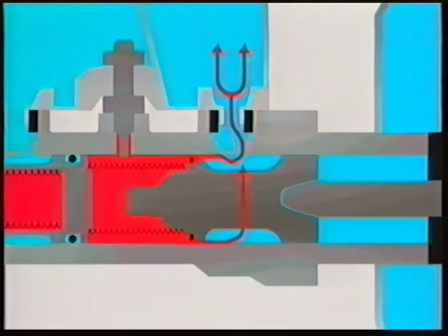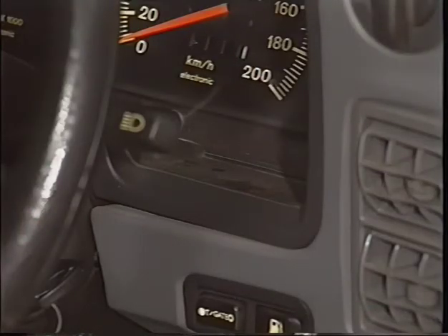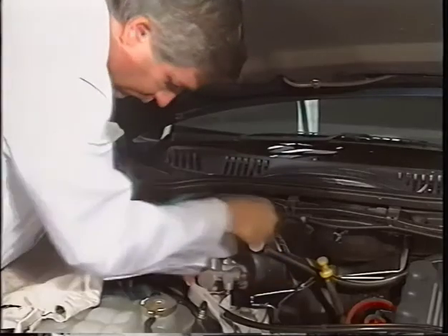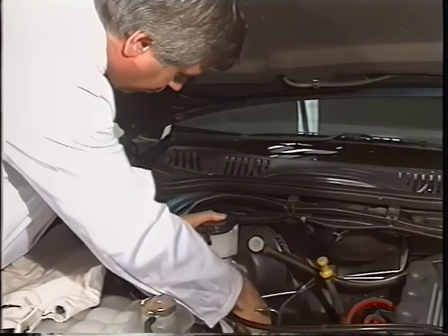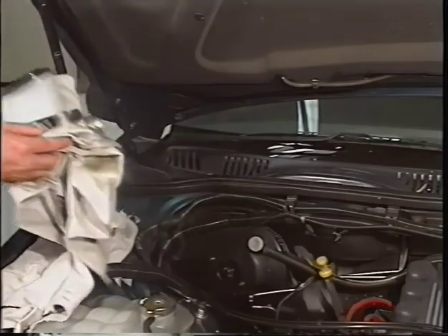Also, on conventional as well as fast-fill master cylinders, internal leakage between circuits or over the primary cups was another cause of low brake pedal problems. This would usually be accompanied by the brake warning light being illuminated. It was stressed that any of these problems would require replacement or a complete overhaul of the master cylinder.